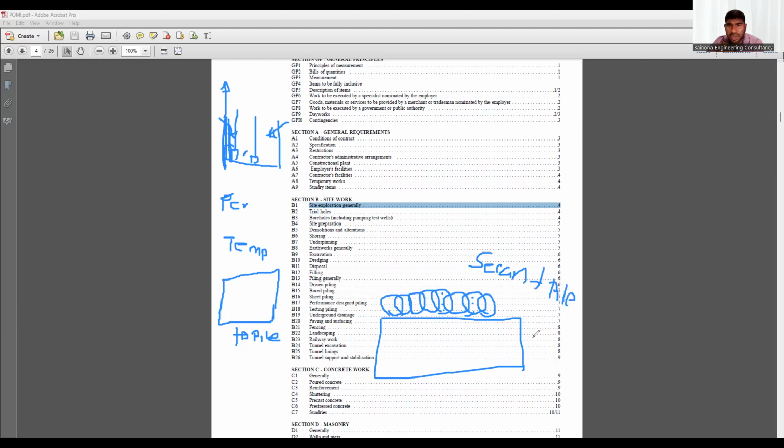These are concrete piles. Another one is a diaphragm wall. A diaphragm wall is also a concrete wall. It's like a panel. They will cast it panel by panel. So if there is damage here, they will just replace it here. If there is huge leakage coming after the shoring, they will replace it here. So these two are mainly used for permanent shoring.